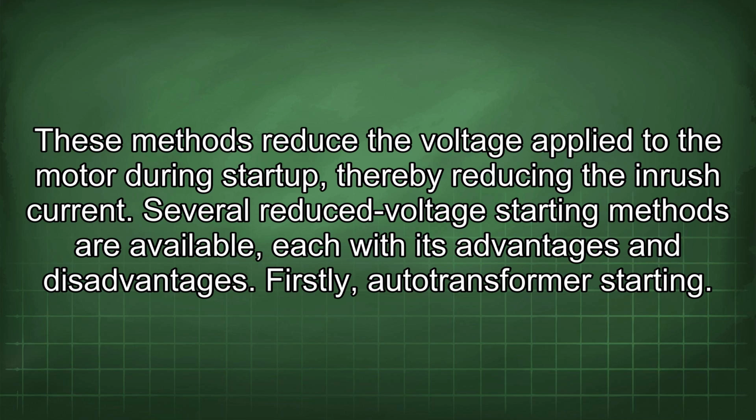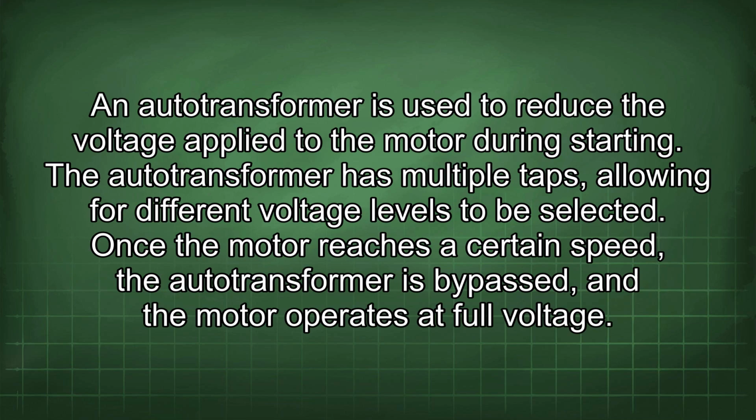Firstly, autotransformer starting. An autotransformer is used to reduce the voltage applied to the motor during starting. The autotransformer has multiple taps, allowing for different voltage levels to be selected.